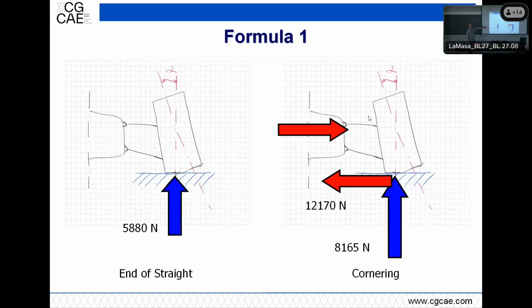You have a friction coefficient which is bigger than 1 for those kinds of wheels. And this clearly is changing this angle. And you might have the situation where the vertical load is pushing to negative camber, and the lateral load is trying to push it to the positive side. It's clear that this variation of the angle is changing what is happening at the tire patch. So it might be that for a too compliant system, the tire is not working in the proper way.